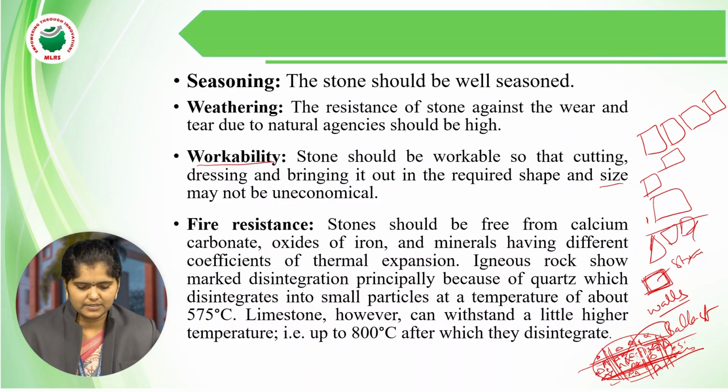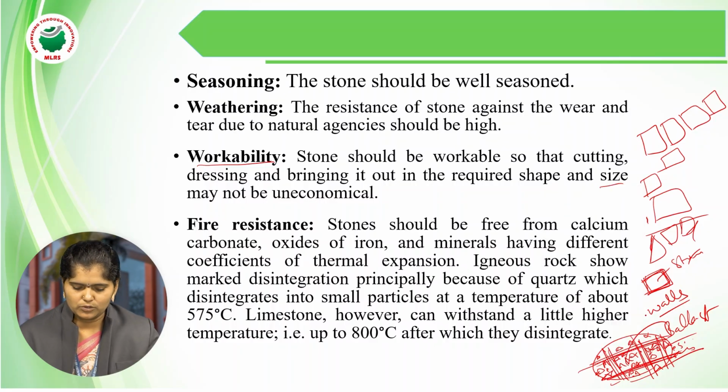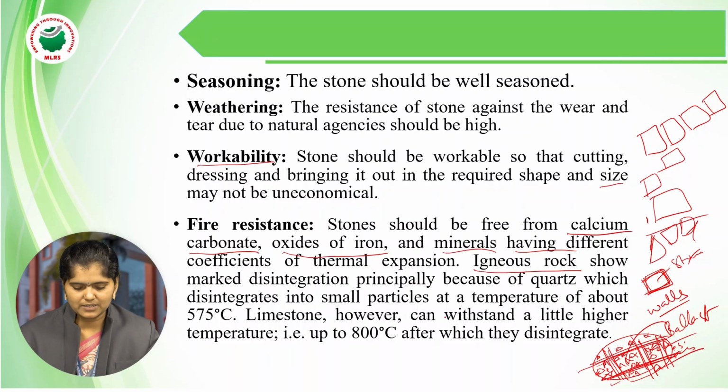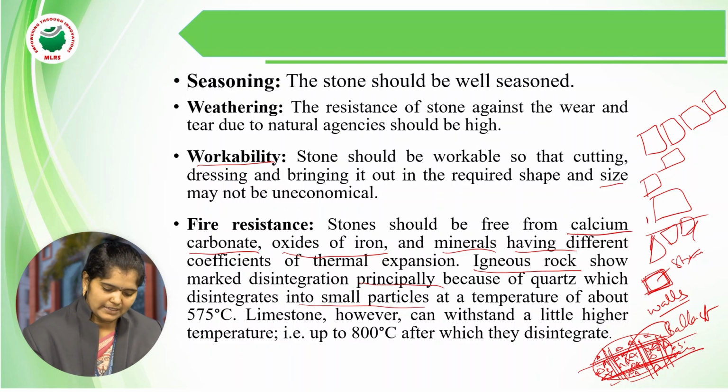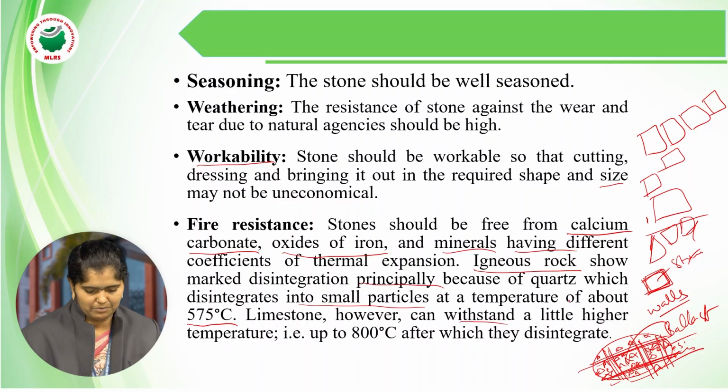Okay, and next, fire resistance. Stones should be free from calcium carbonate, oxides of iron, and minerals having different coefficients of thermal expansion. Igneous rock shows marked disintegration, principally because of the quartz disintegrating into small particles at a temperature of about 575 Celsius. Limestones, however, can withstand a little higher temperature, up to 800 centigrade, after which they disintegrate.